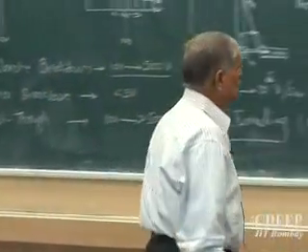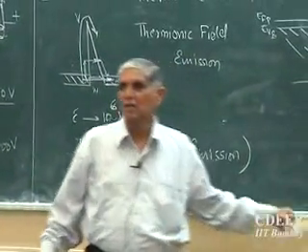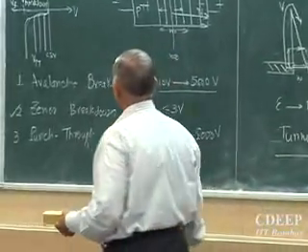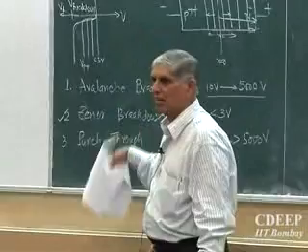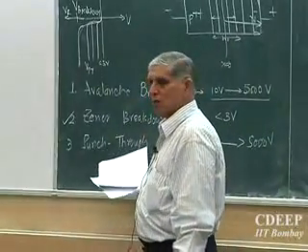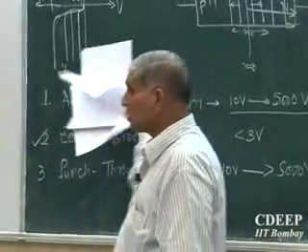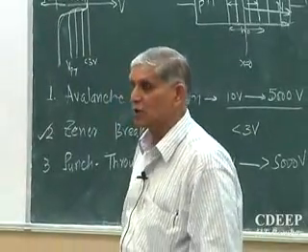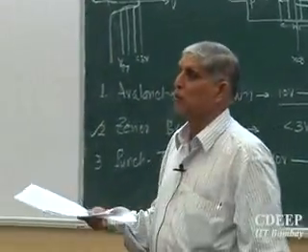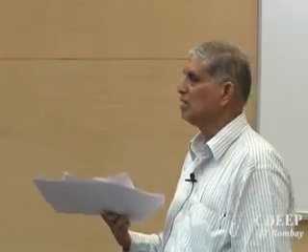Is that okay? So these three mechanisms of device, what we call as the reverse breakdown characteristics, are essentially related to three mechanisms. Which is the most dominant one? The punch through. Most devices will be punch through kind. Unless the breakdown is really 3 volt or lower, because at very low voltage getting a punch through means W will be so small I cannot make the device. Is that clear? Let's say W is required 0.455 micron, I cannot create that. So probably at very low voltage there will not be any punch through device. 5-10 volt yes, but less than 1 volt or 0.8 I cannot punch through.